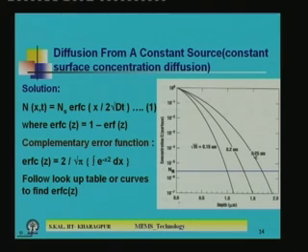That means there are two ways you can increase the product of dt. One is to increase the time, and the other is to increase the temperature. If you increase the temperature, then capital D will also increase. So this is a function of temperature. For this complementary error function diffusion, we use the error function, which is defined by this equation, and its value is not a closed-form formula.